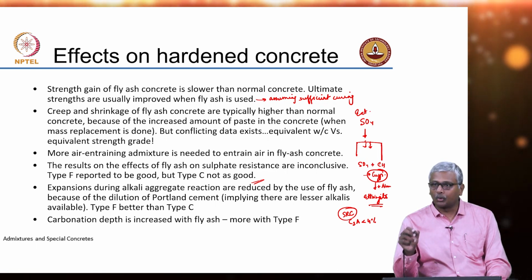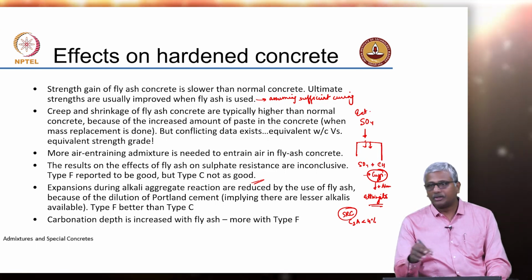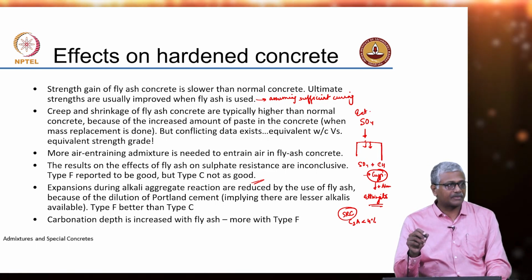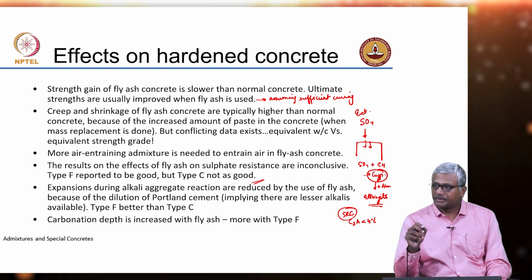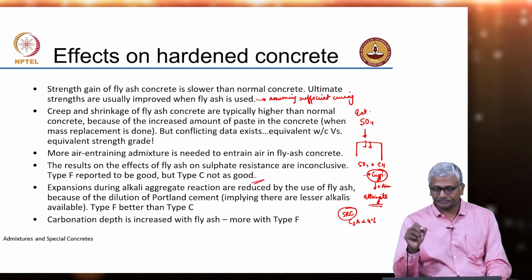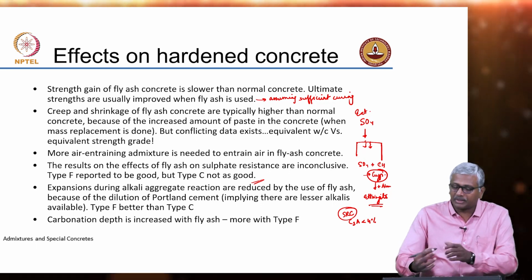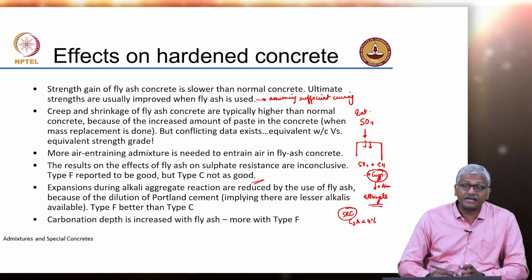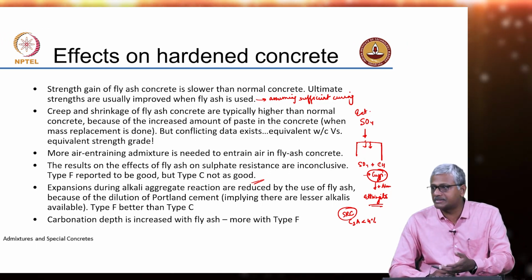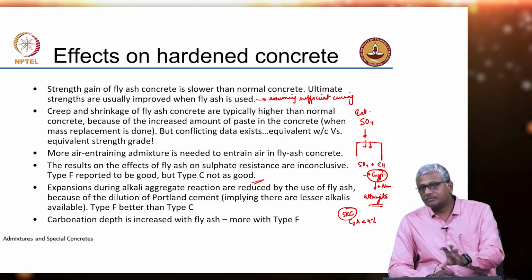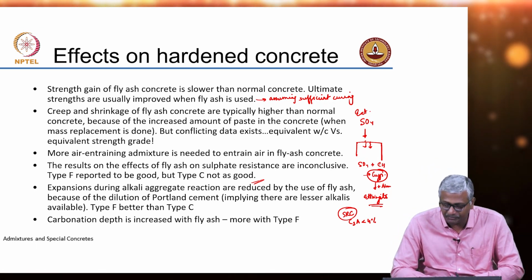When you have concretes with low water cement ratio, it is seen that even systems that have very high C3A contents do not have a problem in sulphate attack. So, the primary emphasis in sulphate is given to the reduction of permeability of the system. Okay. Anyway, that is a separate discussion on its own, but I thought that that level of understanding was important for us to look at why blended cementitious systems can have sometimes very good behavior, some other times not so good behavior with sulphate attack.